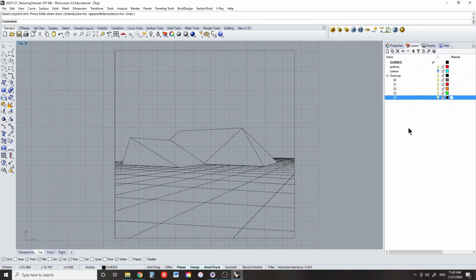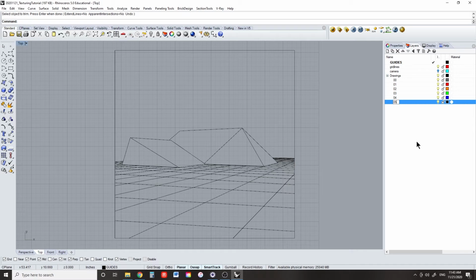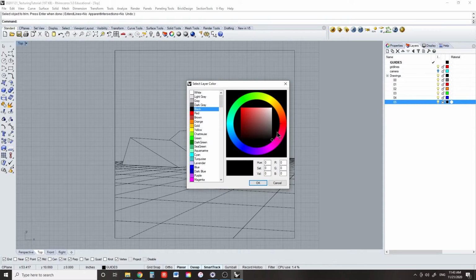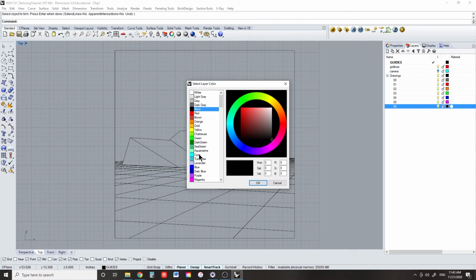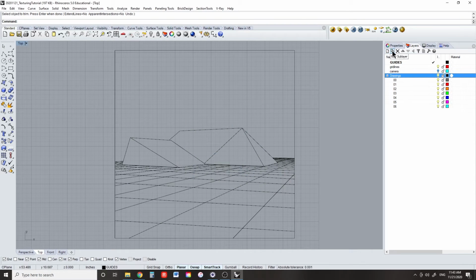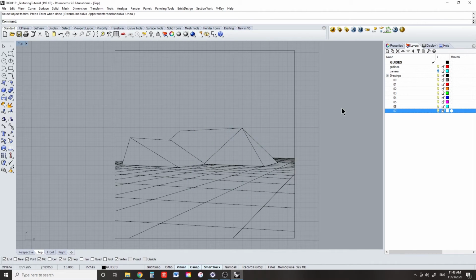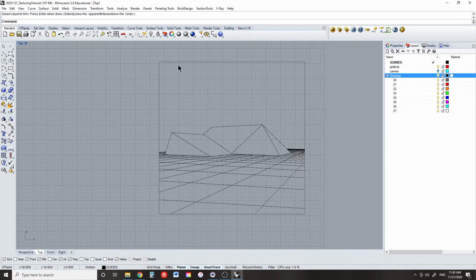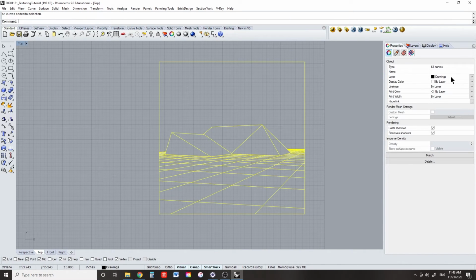You can name your sublayers whatever you want, but I like to name the sublayers according to the line weight that I'm going to assign to them. In my case, I like to name my sublayers 00 through 07. For the sublayer display color, I like to change these to the same colors that correspond with AutoCAD's index colors. Feel free to copy what I've done here for your own drawing templates.